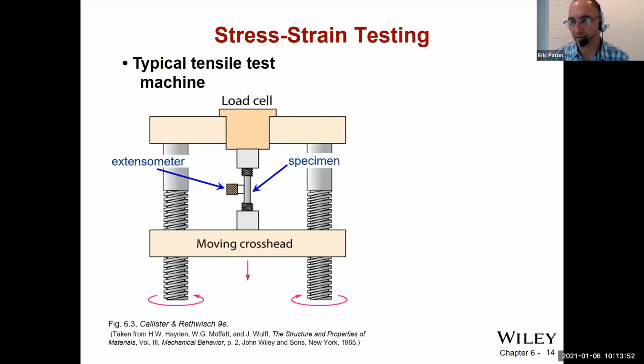So it requires a very slow pull rate because often the strength of materials can change depending on the plastic deformation rate, right? So as long as we keep it slow, then we don't have that additional factor being introduced. That's called strain rate dependency, by the way.